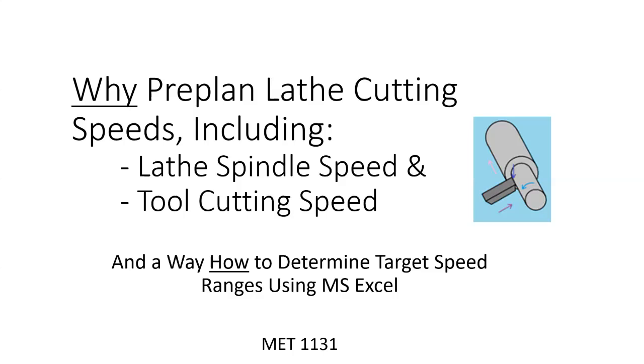So what you're after is, what speed do you rotate the motor on the lathe to rotate the spindle? And what you're after is two things. You don't want to go too fast that it overheats to the point and makes it dull and ruins the tool, or dulls it so it's not so good.